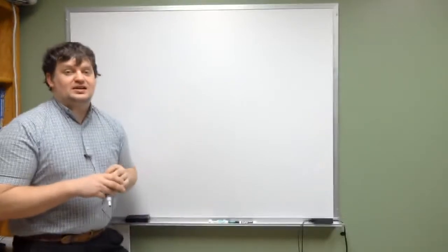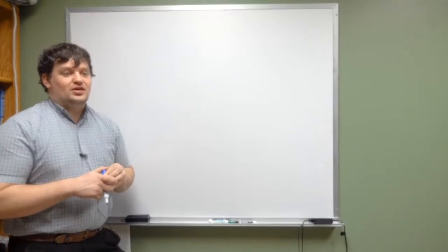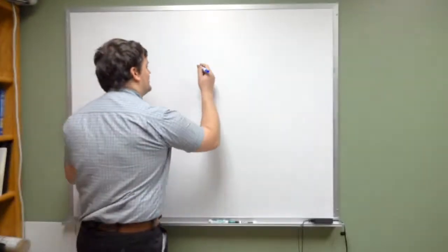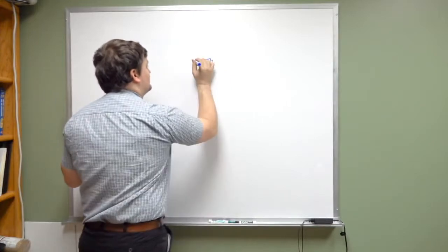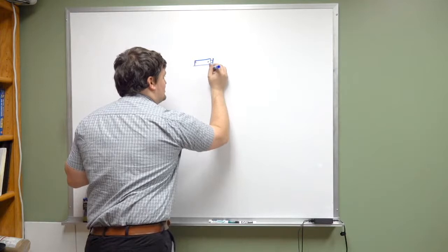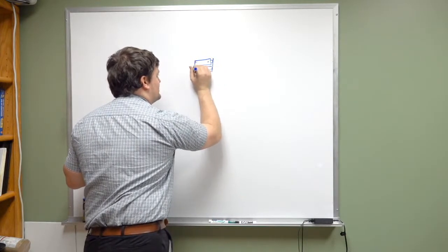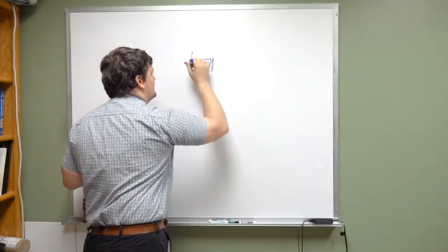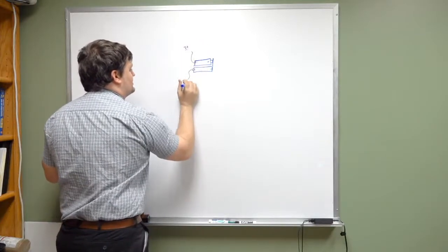The thing about the circuit that I gave you is you can't create 5 volts with 1.5 volt batteries. You can take 1.5 volt batteries, and this is what a lot of devices will do, is here's your negative end, your positive end. They'll take a terminal, and then over here, here's your negative end, here's your positive end. And by doing so, the difference between these two wires is going to be 3 volts.